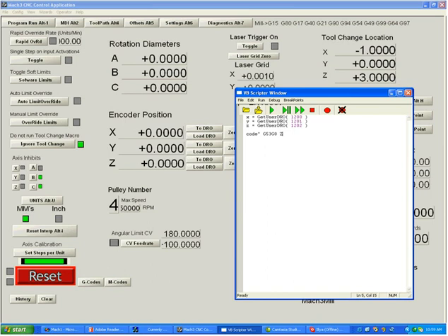And we're going to first move the Z up to its coordinate. So we're going to put a Z and a quote, and this is typical Visual Basic script, an ampersand to join whatever we put there to the Z, and a Z. Now if we were to test this program, what should we get? Well, the X, Y, and Z that we've just read into the program is equal to -1, 0, and +3. This means when we execute our G53 G0 Z with a Z, it's going to take us to Z3. Well, let's see if we can test that.